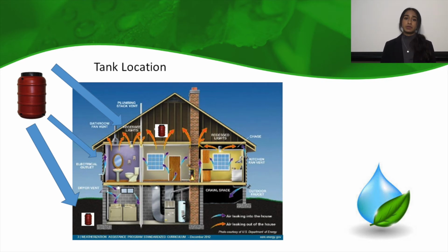Without much invasive plumbing, I wanted to demonstrate a simple methodology to collect the shower water, purify it, and reuse it in the dual water toilet flushing system to investigate odor-related issues, because the most common issue discussed in the literature is a potential possibility of odor of the gray water. My hypothesis is that if you do not store the shower water for too long and drain it out regularly after using it for toilet flushing, there should not be any odor issues.